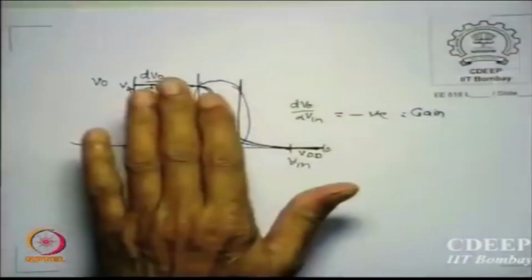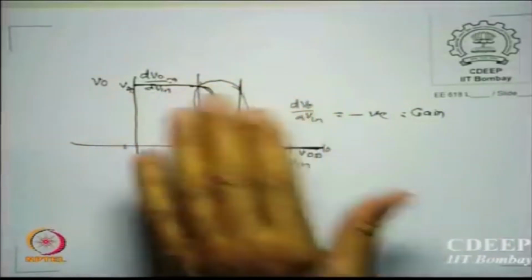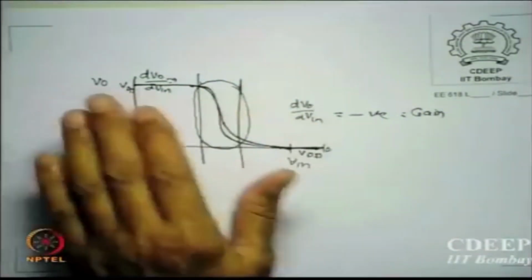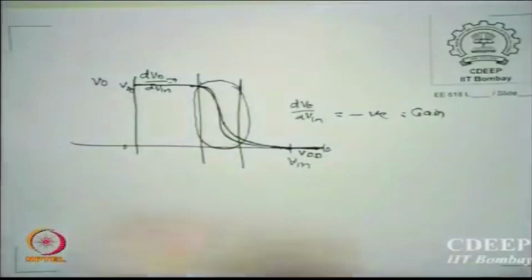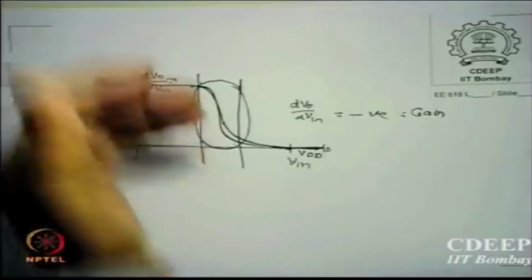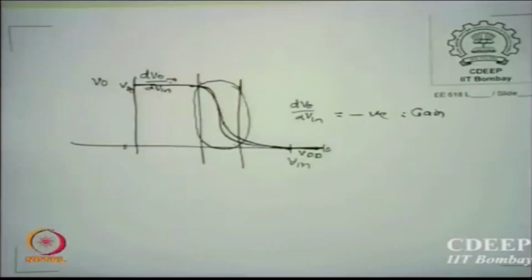Is that clear to you? So the transistor must remain biased in this region to keep amplification. In digital you don't bias because you are not interested in gains anyway. Of course it does have influence on speed, margins. I am not trying to say digital does not get affected by that. In fact, depending on size, it may shift and it may reduce the margins as well. But typically in digital we don't care much because we are only interested in the 2 ends. Okay.